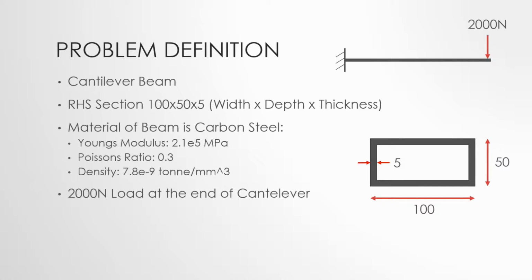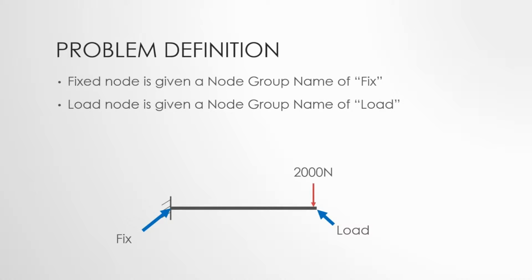The mesh for this FE analysis is in MED format. In this mesh, the fix node is given a node group name of fix, and the node on which load is applied is given a node group name of load.